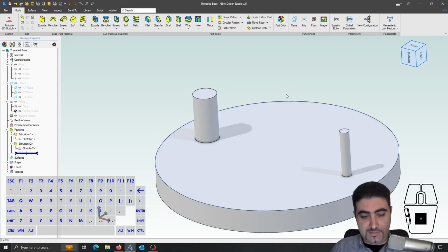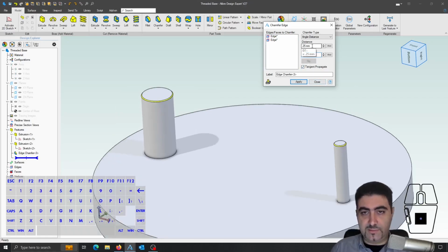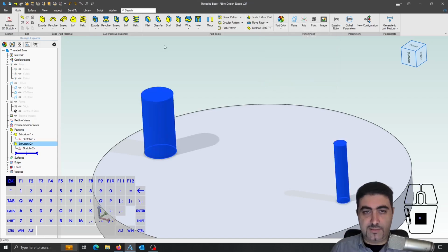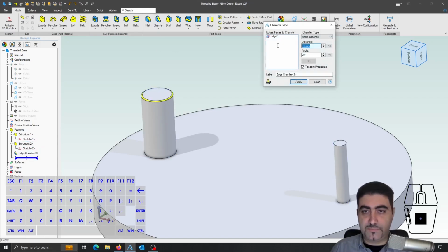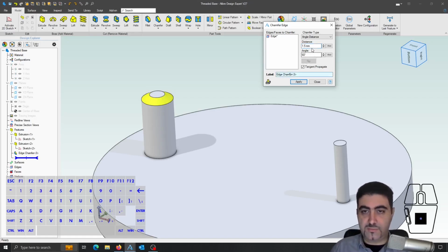Okay, let's get the chamfers going because, as we said, it is best if we get the chamfers going ourselves. Yeah, to be honest, you need 2 different chamfers here. So this is an M10 by 1.5. The chamfer should be a bit more than half the thread pitch. Or should I just give it a thread pitch as a chamfer? Let's see. 1.5. That's too much. That's fine. Oh, wait. 30 millimeters. Yeah, the other way.